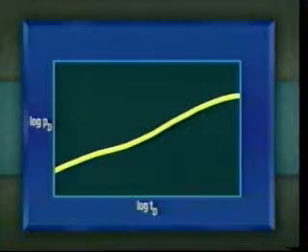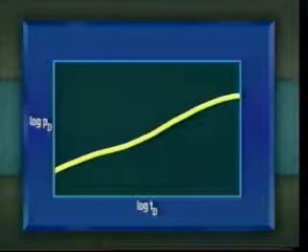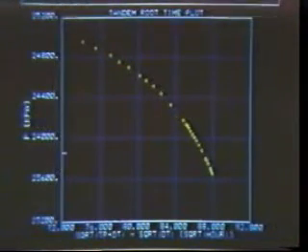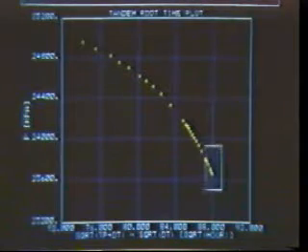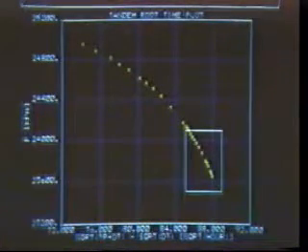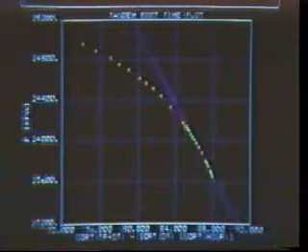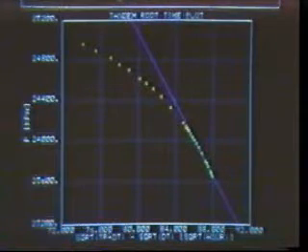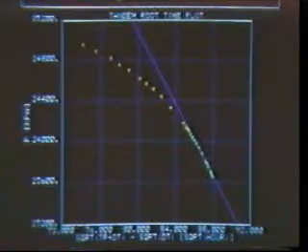If the wellbore storage effects are not significant, a bilinear flow analysis or a linear flow analysis may be undertaken to determine fracture length if the data support these regimes. For example, from measurement of the slope of the line on the tandem square root plot, fracture half-length x sub f can be determined, provided that we have on hand an estimate of the permeability value. Once pseudo-radial flow has been achieved, conventional methods can be used to determine KH.